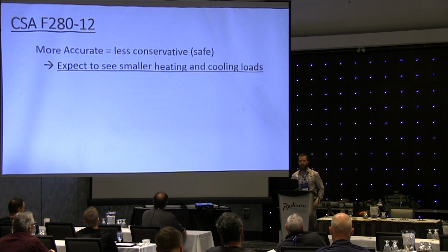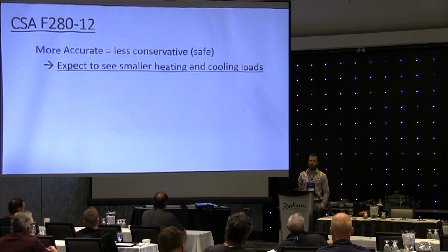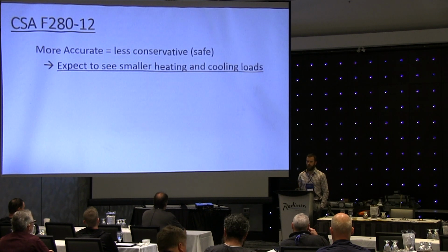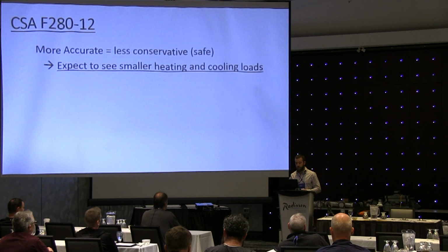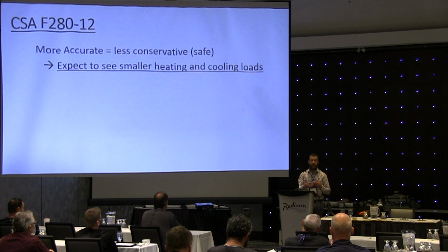I had an energy advisor telling me that they had designed to put in a 70,000 BTU furnace, and the energy modeler came out with 26,000 BTUs, I think. And he brought this to the mechanical contractor's attention. The mechanical contractor said, "You're out to lunch. 26,000, no way." That's how much difference they're seeing sometimes. So be aware of that, and it's okay so long as we're checking the actual methods. We're not tasking inspectors with reviewing the calculation methods. You just need proof that they were done.